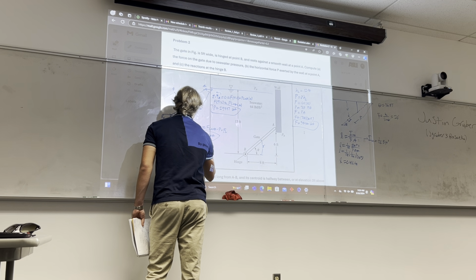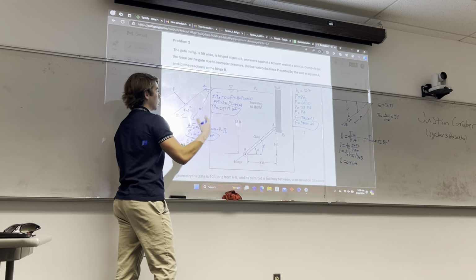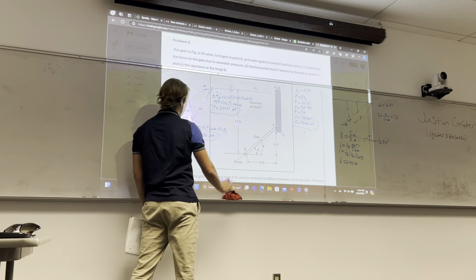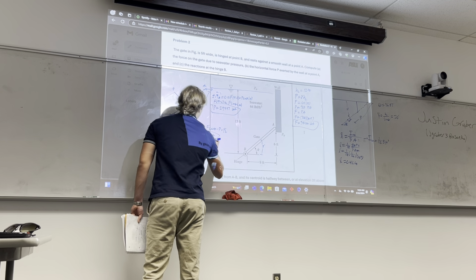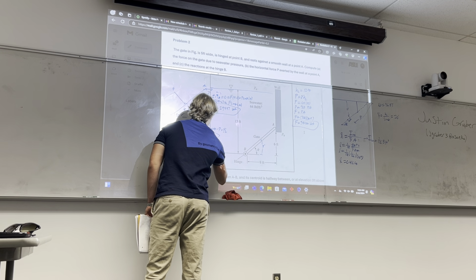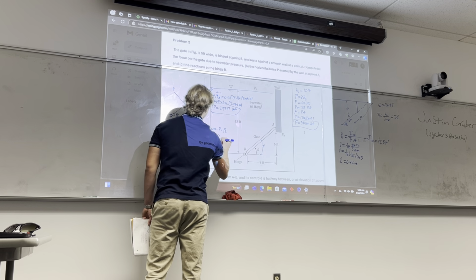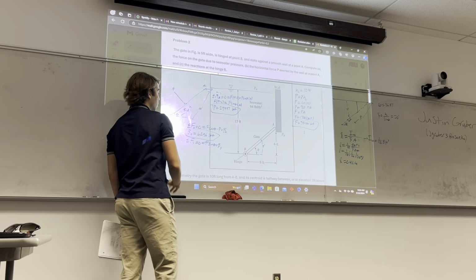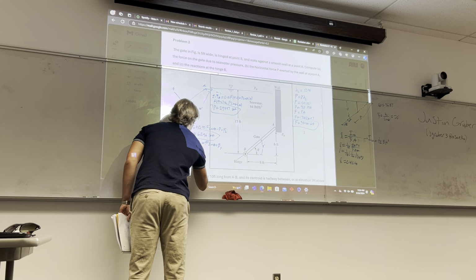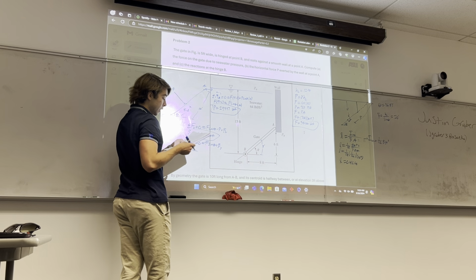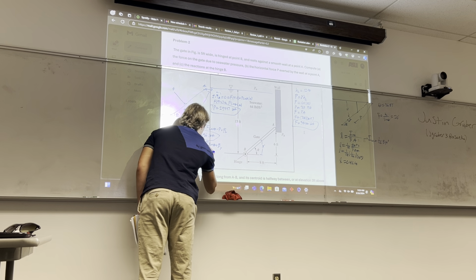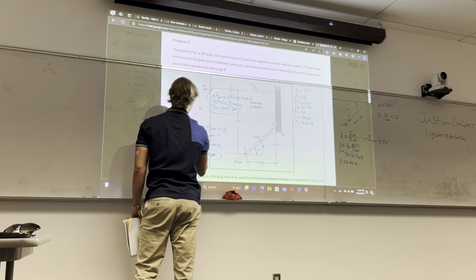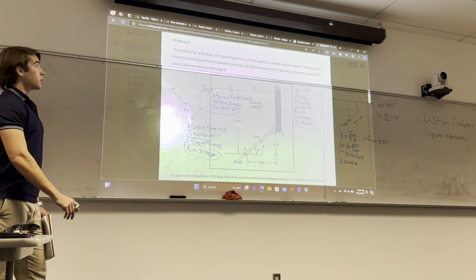There's that. Now, same thing for BY. Sum of forces about Y is 0. And we obviously don't care about the force of gravity. We're neglecting gravity for the normal reactions, stuff like that. So negative F sine theta plus BY. Obviously, there's no component of P acting in the vertical direction. So plug in, you get BY equals 38,719 pounds again. Cool. All right. Now we've got everything. Should be good to go.